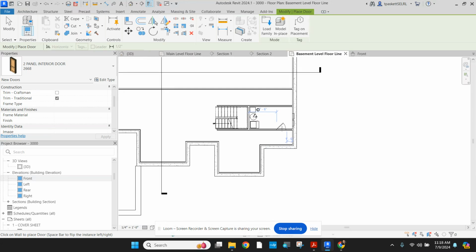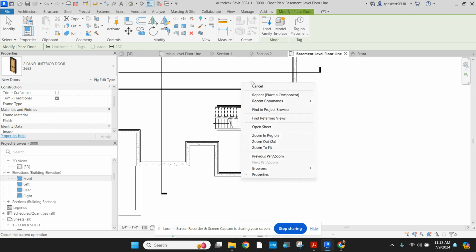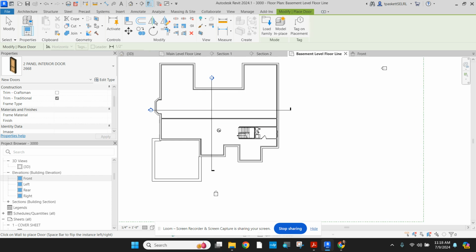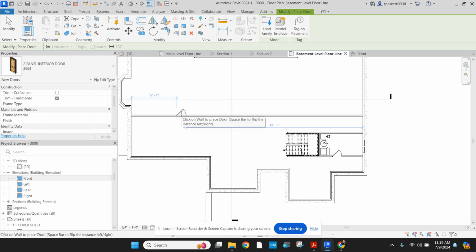And I think I put it here. Well, got a couple of rules. The door cannot open in front of the power panel, so it's got to go here, and we'll go from there. Now, the rest of this space, you can feel free to do as you will. I'm just going to throw a couple of doors in this wall, just for egress. They can be moved and redone as needed, depending on what your layout is. But you have to be able to get from one side of the space to the other. So we'll go ahead and throw those in just to make that accommodation.